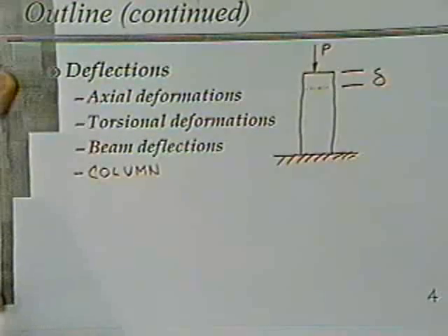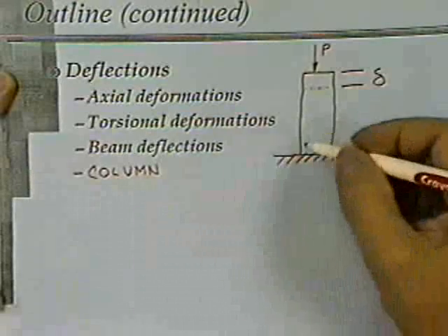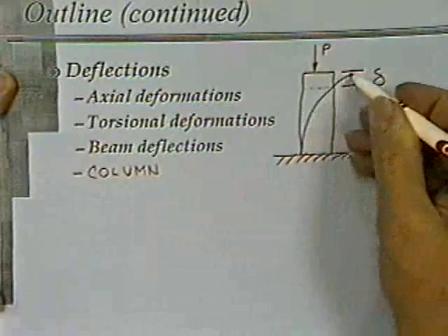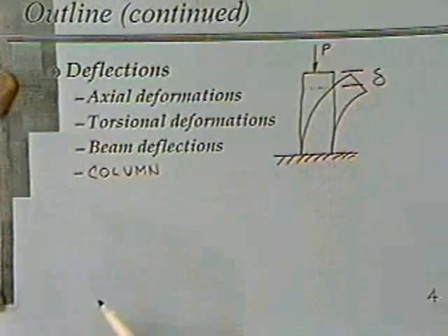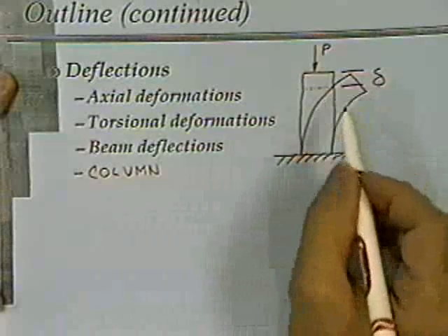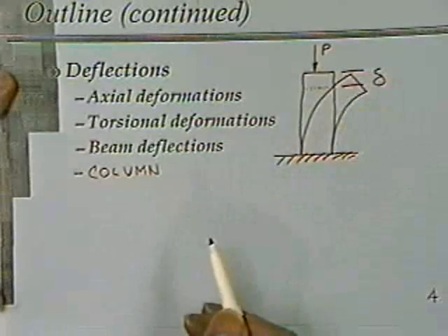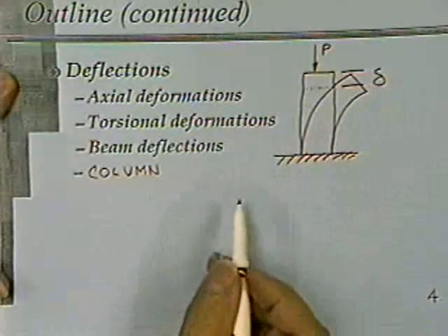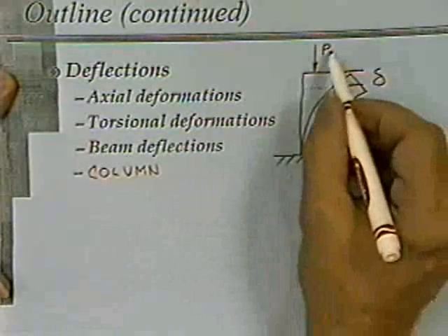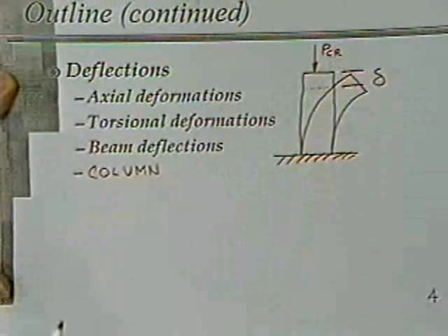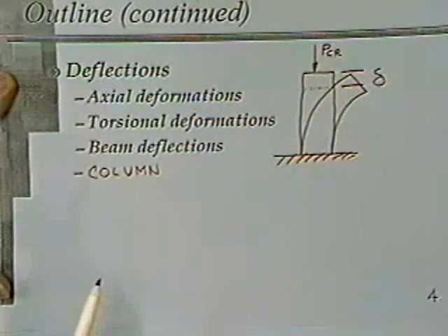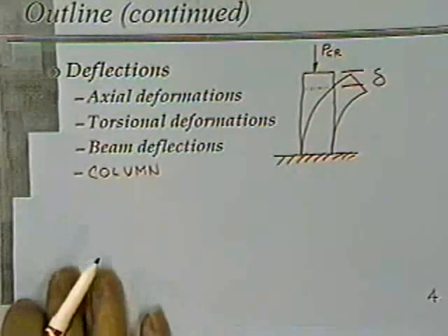Now, in a column, that also happens, but again, it's a very small number. This kind of deflection in columns is what I'm talking about. That kind of deflection is failure, when it has dumped the load off on the floor. So although this number can be calculated for various loads, it's usually of not much interest to you in the design phase, because your interest is to make sure that this critical buckling load is stayed well away from. Okay, thank you. Okay. Got it.